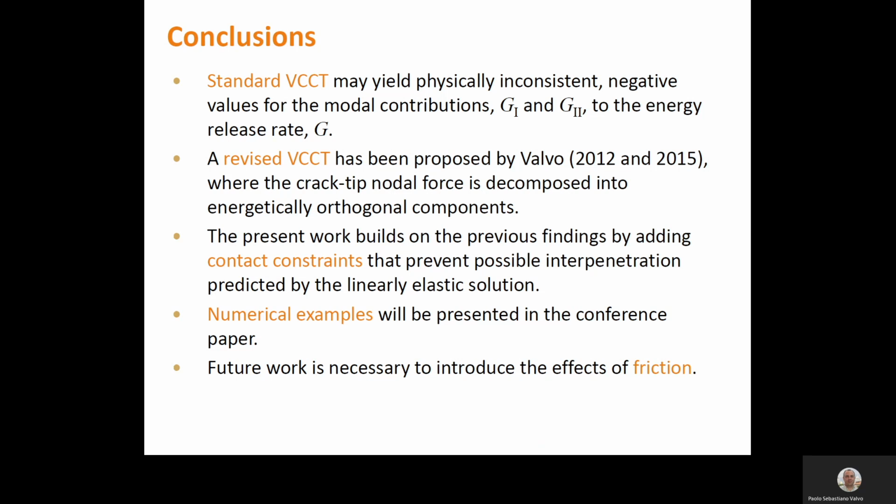However, such a revised formulation does not take into account the shortcomings from possible interpenetration of the crack faces, which may be predicted by the linearly elastic solution.